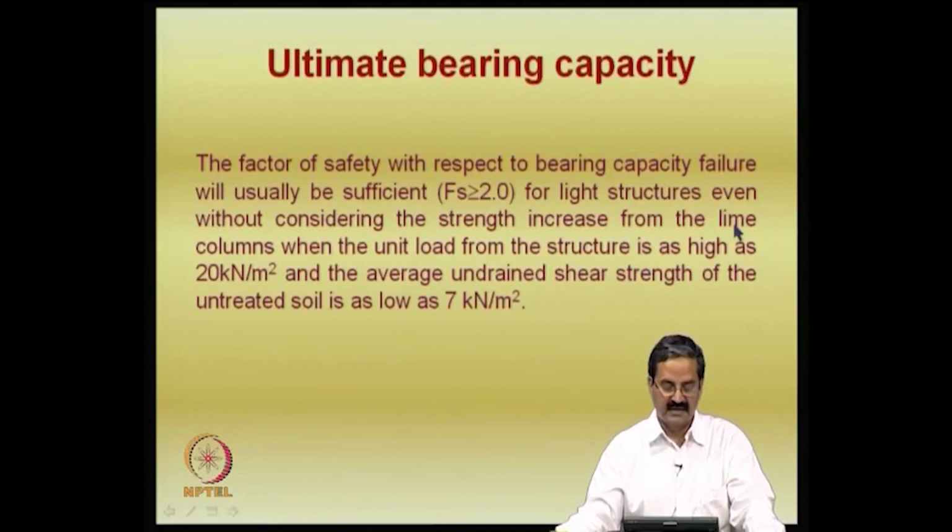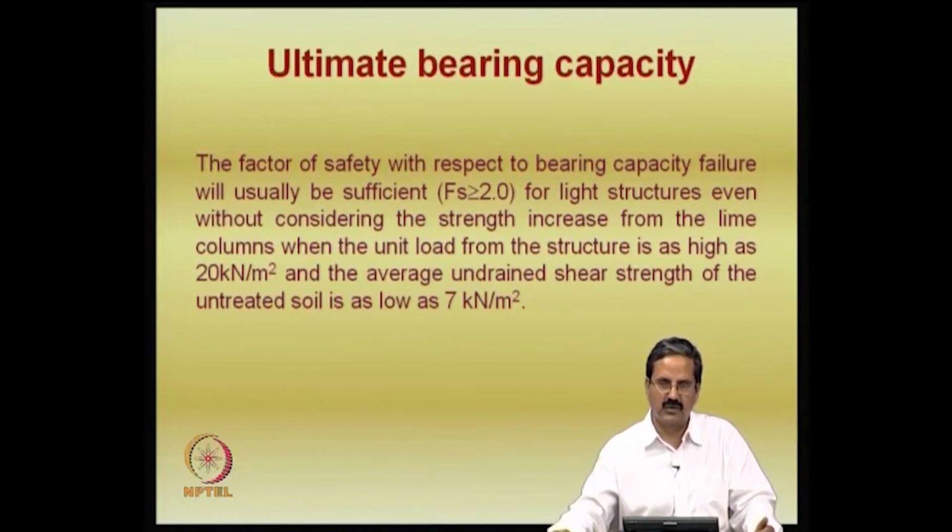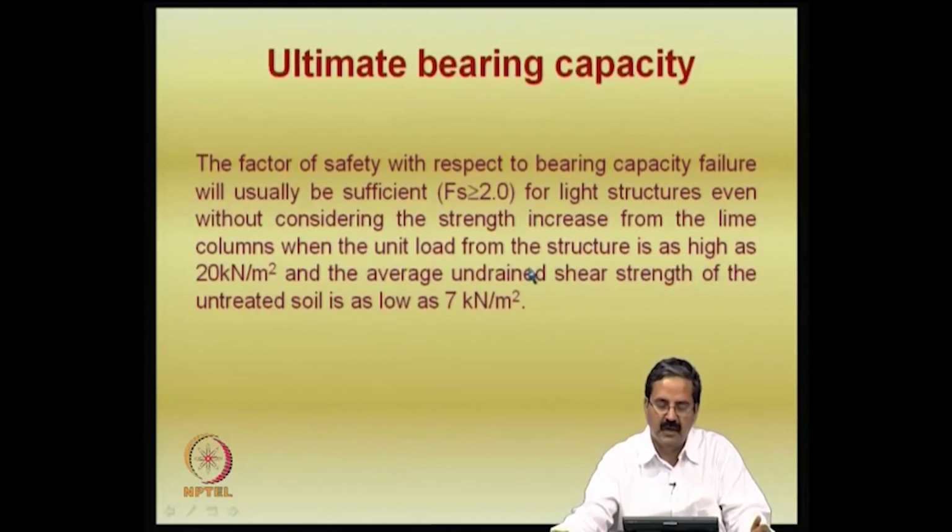In this we do not consider the strength increase because of other chemical reactions and all that. We also do not give importance to the overburden effect. As you go down, definitely the strength improvement is going to be higher, but we will not give importance to that, and we just take a conservative design that the strength is the same with depth. So, that is a conservative assumption.